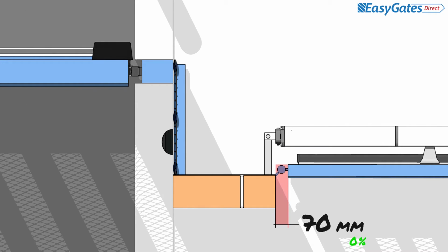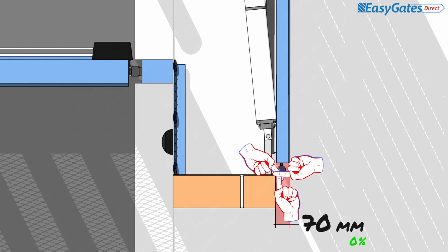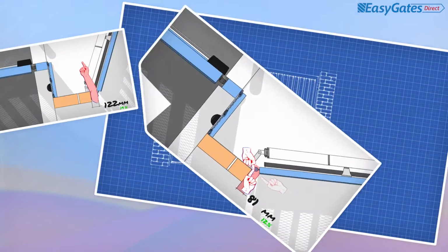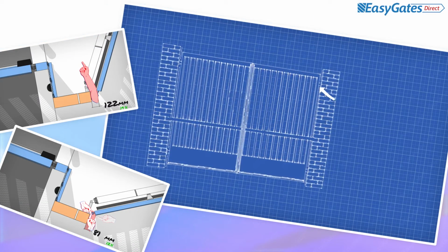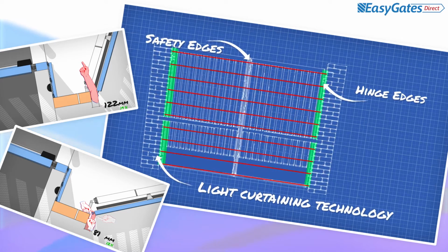The Code of Practice also defines that where the hinge gap in a swing or bifold gate is constant and between 25 mm and 100 mm, then this can be considered safe. Remember to note, all other hazard areas of the swing gate must be assessed separately and designed out or eliminated where possible. When addressing these crushing or shearing hazards, care should be taken to select an appropriate solution that eliminates or reduces the risk as much as possible.